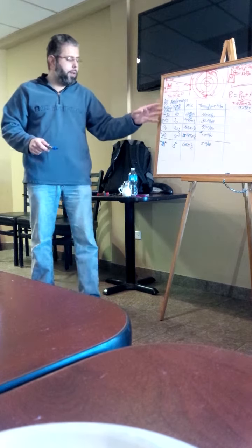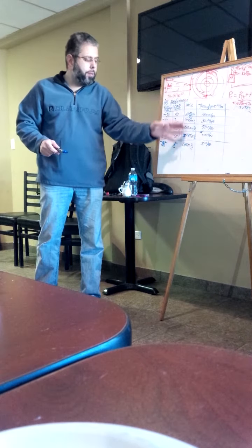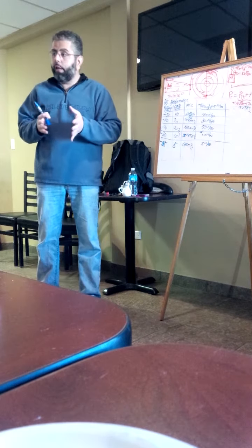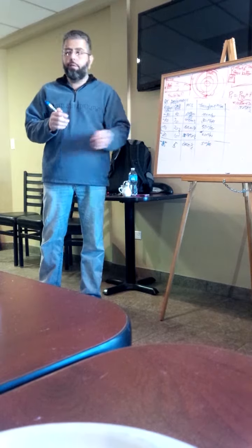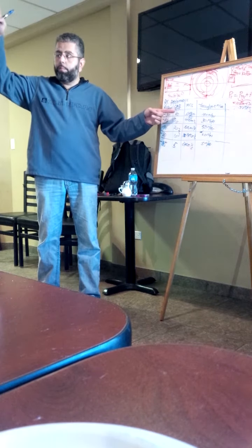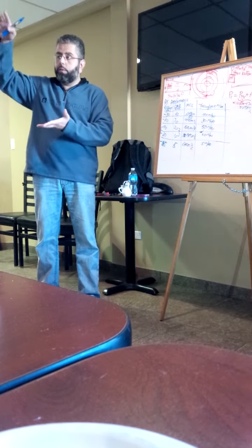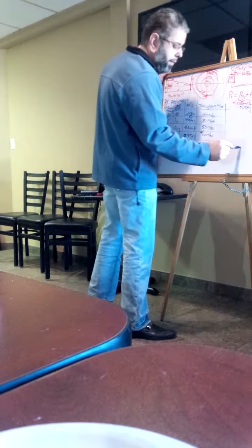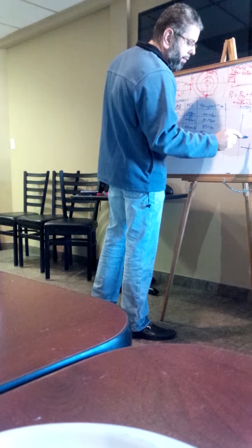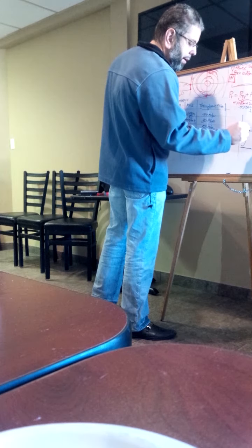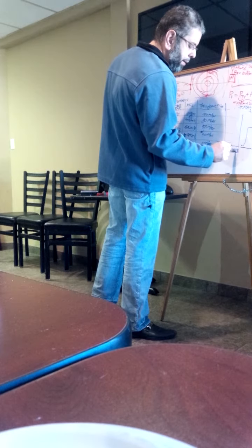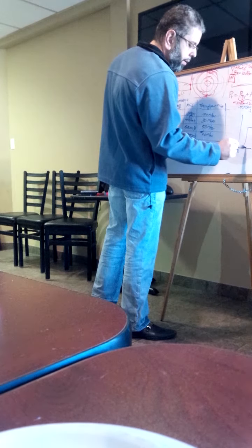So as I said, real high level, this was just power. MCS just says how tightly you can pack your data. And you can pack it more tightly when you have less interference and less noise. Noise comes with power. As you bring power down, you get closer to noise. Remember we said noise floor last time? If this was your noise floor, we didn't have a chance to draw it, but we were kind of hand waving. If this is your 20 megahertz signal, and this is the noise floor that just comes from KTB, we'll just call it that.